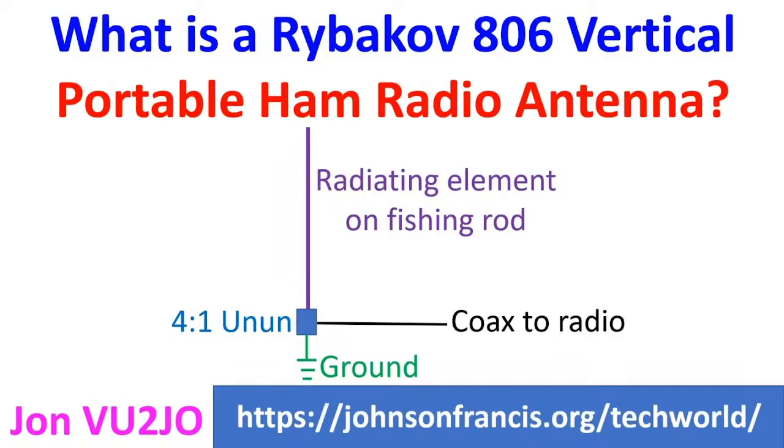IV3SBE, who designed it, describes it as a little miracle which is only 1.6 meter when not in use and 9 meter when fully extended and weighing only 2.2 kilograms. 8 meter wire is used with a 4:1 unun at the feed point. Unun by definition matches an unbalanced antenna to an unbalanced feed line. Here it is used to lower the impedance of a random wire antenna.